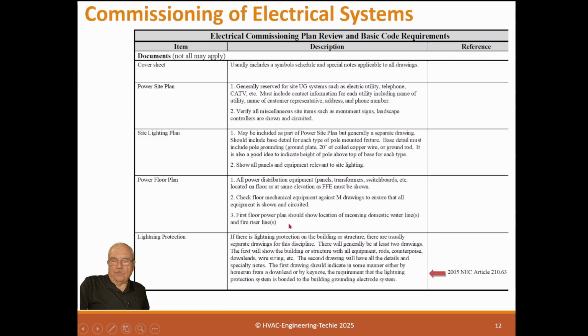Now there's been a code change here. One of the code requirements is that the electrical grounding be grounded to the incoming water. It used to be the fire line was also included, but that has been deleted. So nowadays, the fire line is not required for electrical entrance.